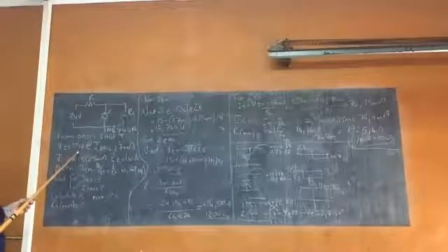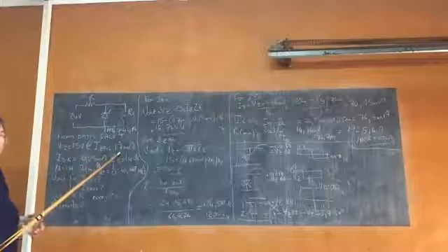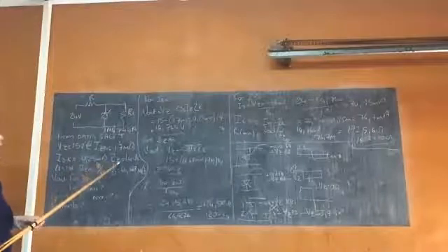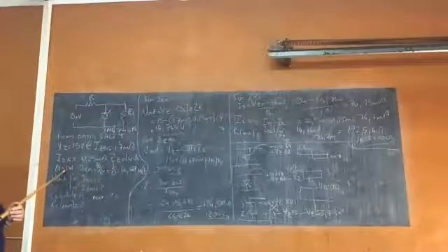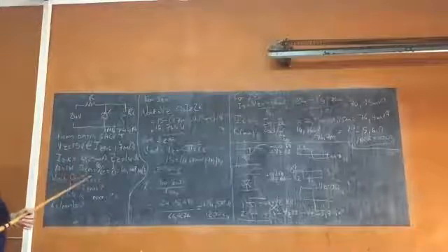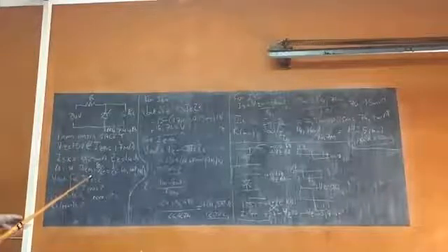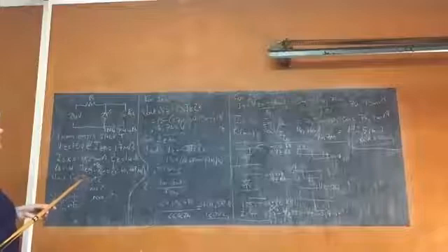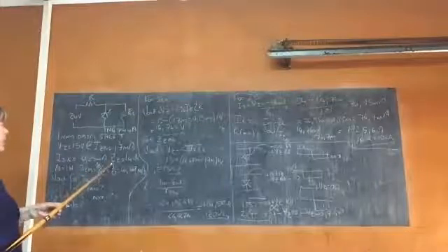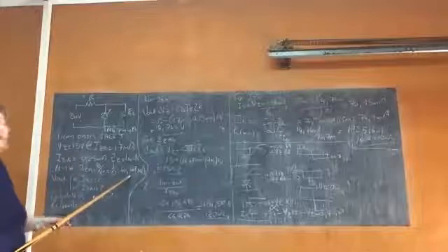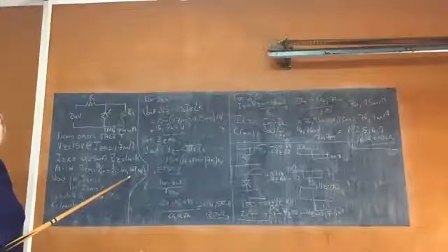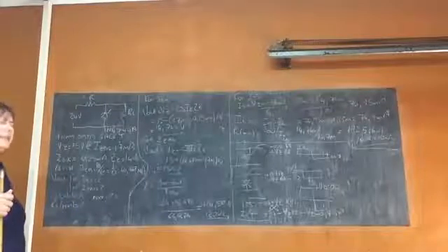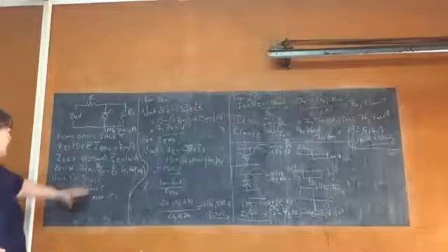VZ 15 volt at IZ 17 milliamps, IZK 0.25 milliamps, ZZ 14 ohm. The power dissipated is 1 watt. And you can immediately do this calculation because you always need to know what IZM is. So you can immediately do PD over VZ, 1 over 15, and get your IZ maximum, the maximum current of your reverse biased Zener.